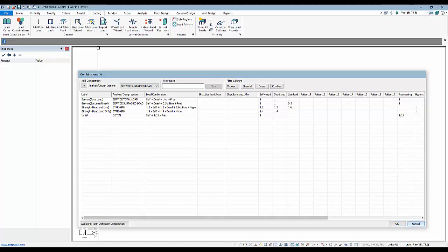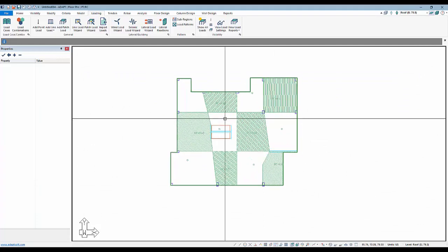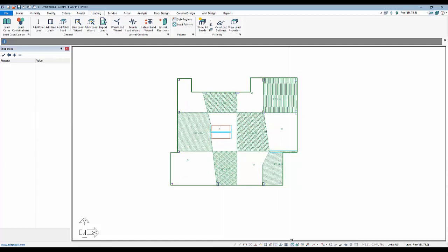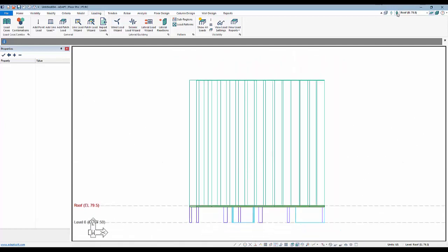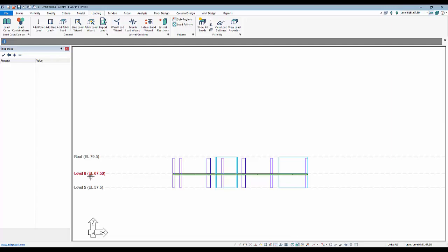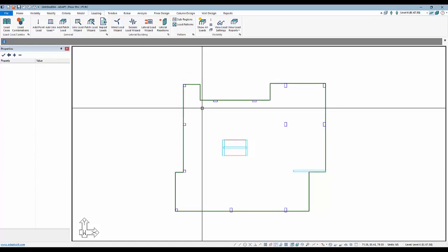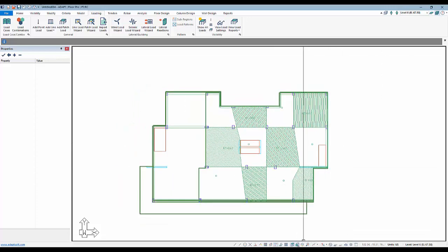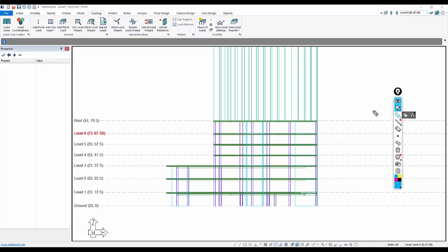One thing to note is the skip and the pattern loading was built in a legacy format for individual slabs, so for single level slabs. Now if you have multiple level slabs, if I, for example, wanted to add patterns to this level, level 6, I could create subregions or copy subregions down and create additional load patterns at a separate level. So let me go back to a multi-level view, and I'm going to mark this up. So at the roof level, we have 7 load patterns.